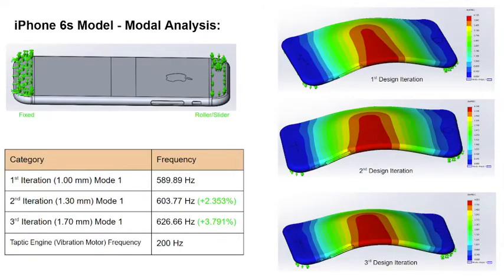A modal analysis is performed to see whether the resonance frequency of the structure coincides with the taptic engine's frequency. All three iterations perform well, with the first mode being much higher than 200 Hz.